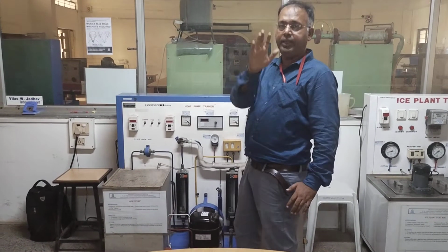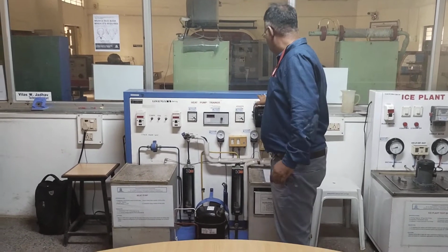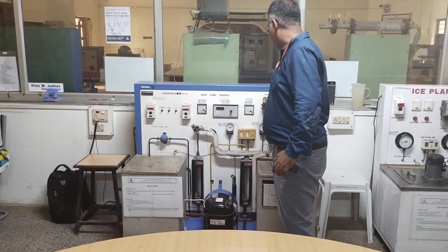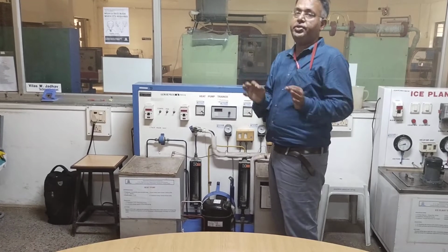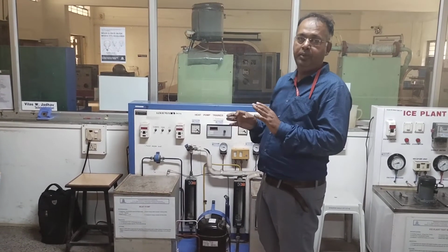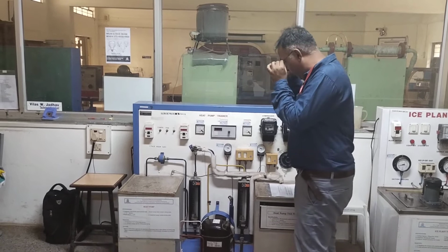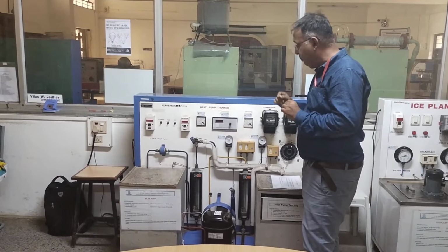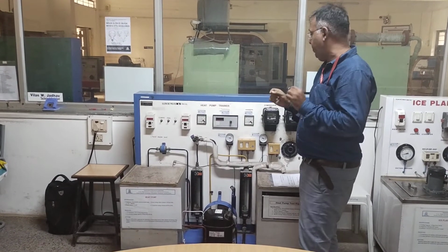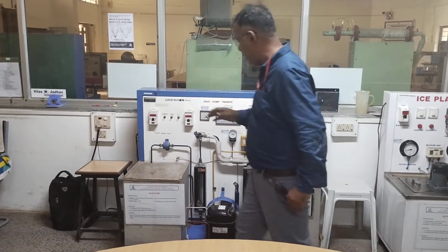MCP delta T upon time, upon the power consumed by the compressor, would give you the coefficient of performance of this heat pump. Okay, this coefficient of performance can also be calculated by using the pressure enthalpy chart of the refrigerant which is used. Okay, so let us just discuss it in brief using the board.